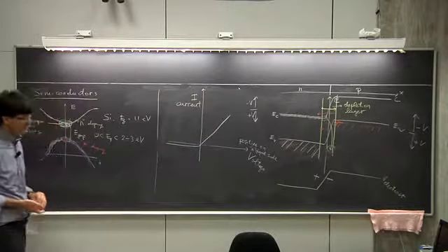Okay. Good point. No, it starts from 0 because this is the external voltage. I'm not including the built-in voltage. It must start from 0, right? It must go to 0 because if you're talking about the external voltage, there can only be current if you apply a voltage. It cannot be a spontaneous current without a voltage. So this has to go through 0. If I'm including the built-in voltage, of course, it's a different story. It's offset. But I'm talking about the external voltage, so it has to go through 0 here.